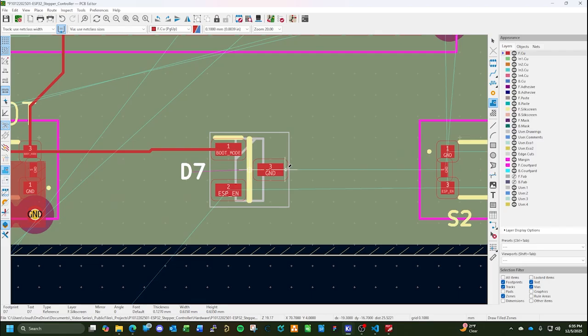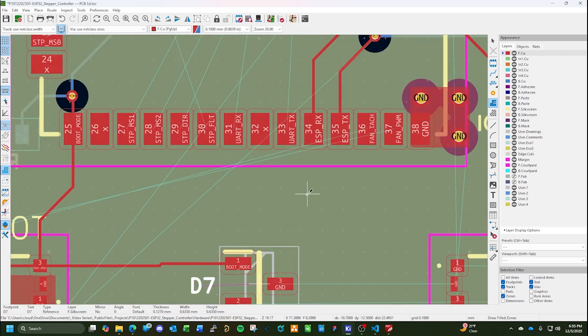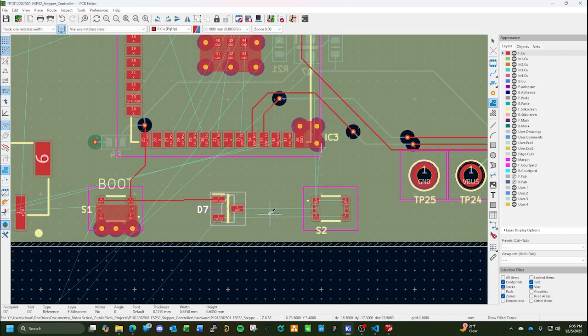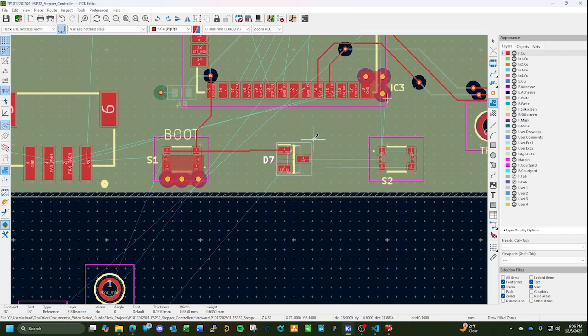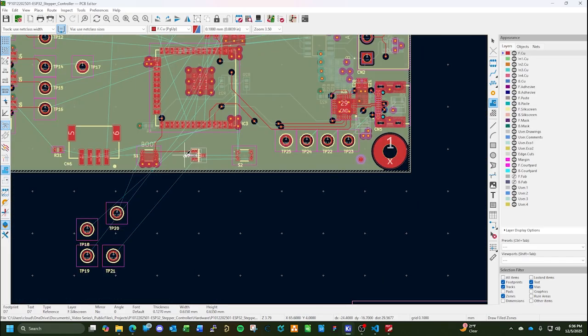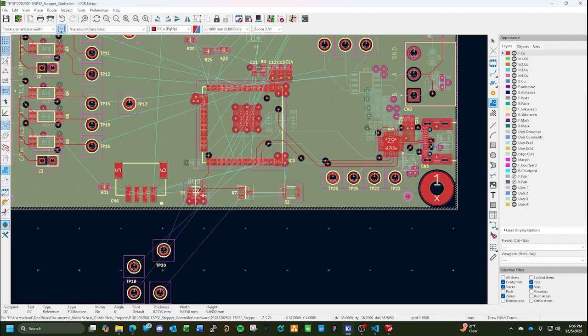It's what's called a transient voltage suppressor. It's a special diode designed to take that extra voltage and sink it to the ground plane in an attempt to protect the rest of the circuitry. It's always good practice to throw a TVS onto anything that humans can contact during normal operation, testing, or development. So if you've got a switch or a button, you definitely want to try putting a TVS diode on it, especially if it directly interfaces with a microcontroller like an ESP32.